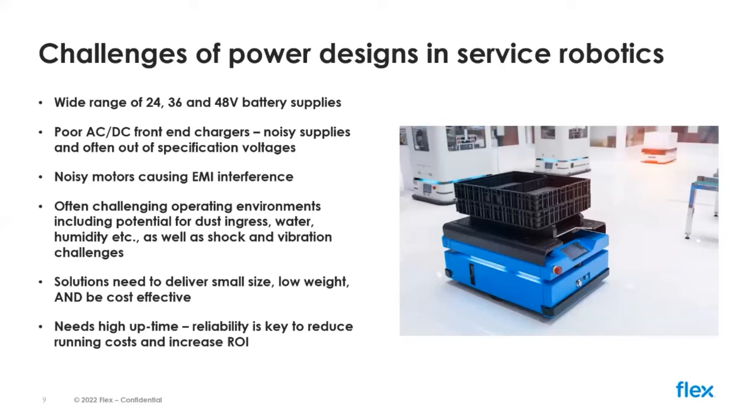So, typically these are operating in the same environment as human beings would be. So they're not military grade or very, very dirty, but there can be dust ingress, humidity, water ingress, for example, as well as just shock and vibration. So, again, from a power supply perspective, we need to be able to deal with that sort of shock and vibration requirements on the whole.